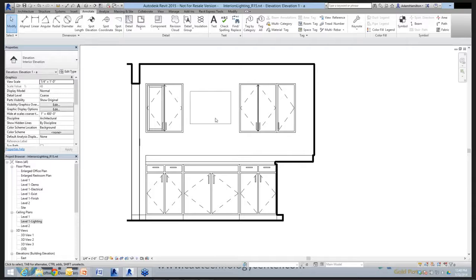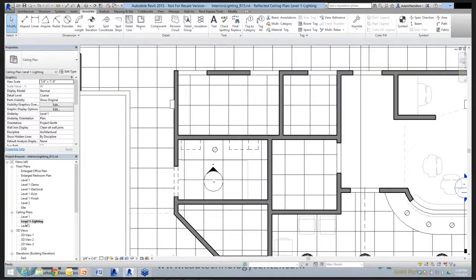The other thing to note is that in CAD, we had the ability to create center lines because inside a room, this particular back wall, you'd be able to find the midpoint between a lot of these things. Well, because of the nature of Revit and the fact that this wall isn't just this room, but actually spans multiple rooms, the midpoint is not easily accessible or at least relevant to our space.